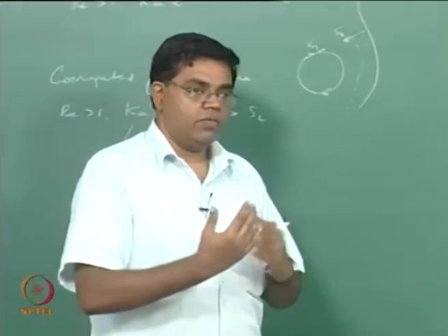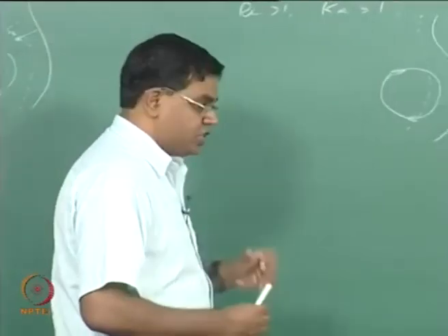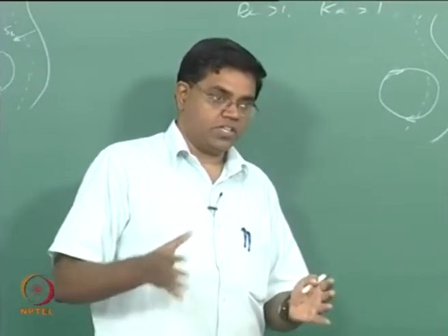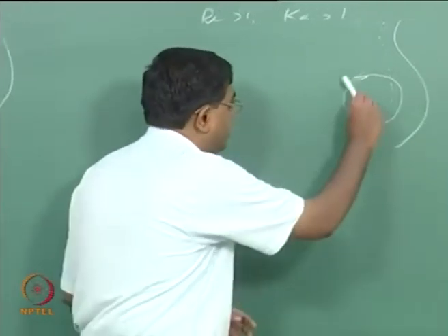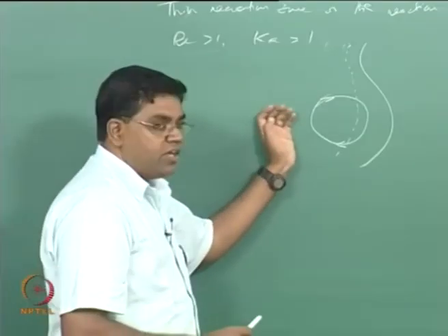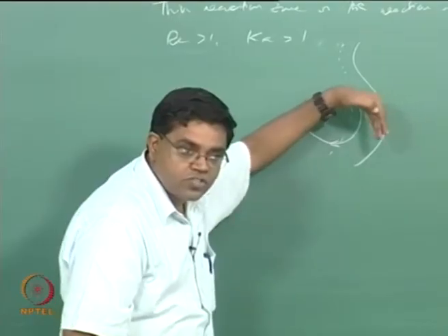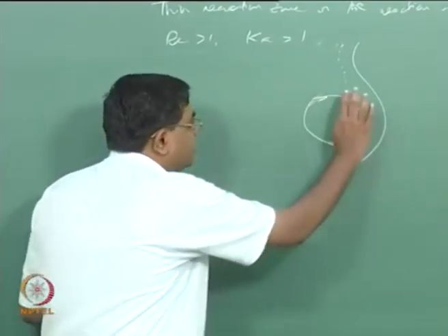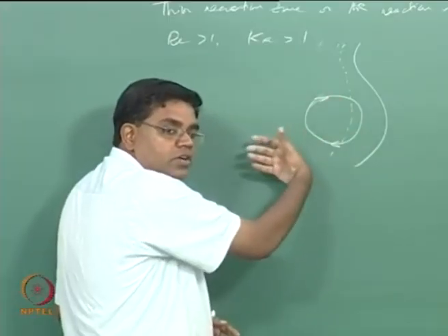So you have a heat and mass transport that is happening in the preheat zone, which is now in addition to the molecular transport that happens because of temperature and concentration gradients, is also additionally happening because of the eddy. That means this eddy is now taking the reactants and putting it into the preheat zone for the reactions to consume and taking the heat from the preheat zone and bringing it a priori ahead to the reaction zone and